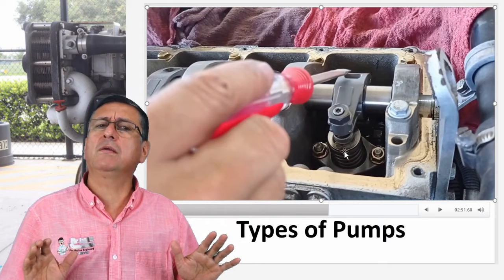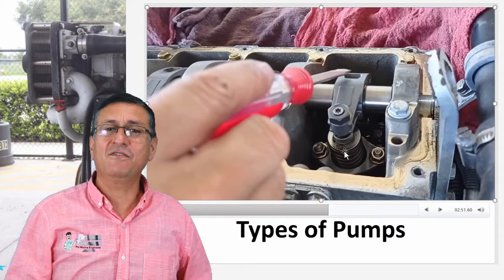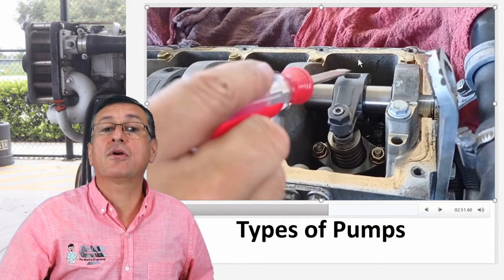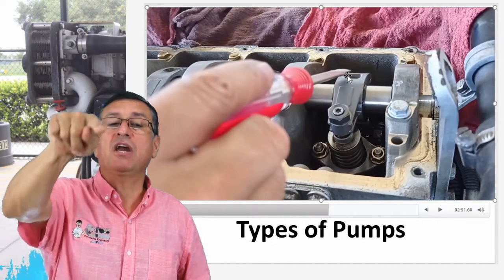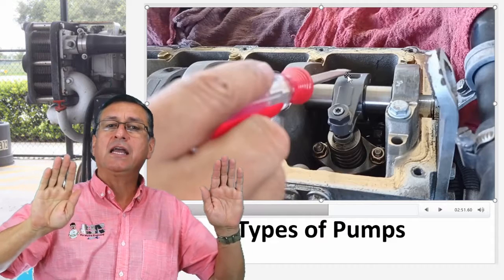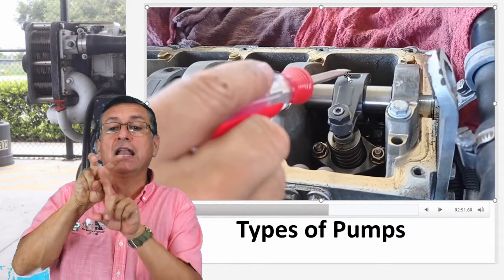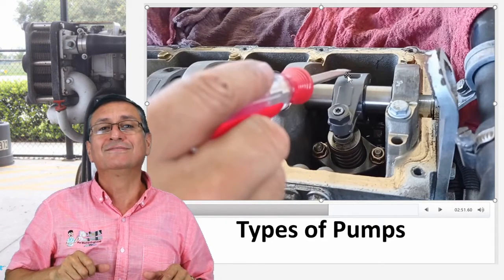Mechanical injectors. What is the meaning of that? Those injectors open and close for a mechanical system. The mechanical system is this: a rocker arm. The rocker arm is activated by the camshaft of the engine. The camshaft has lobes for the valves, intake and exhaust, and other lobes in the middle for the rocker arm of the injector.